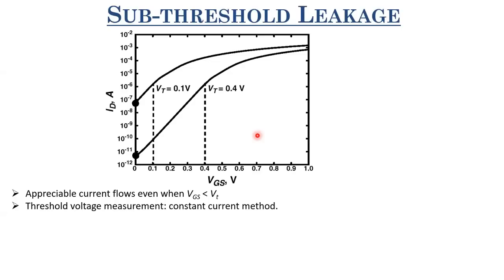But the concentration of the inversion layer is something that is not measurable. You cannot measure it by any technique in situ. If you have a MOSFET in your hand, you cannot measure the inversion layer concentration. So that is not something which is measurable, and that is just an academic definition. How do industries measure the threshold voltage?